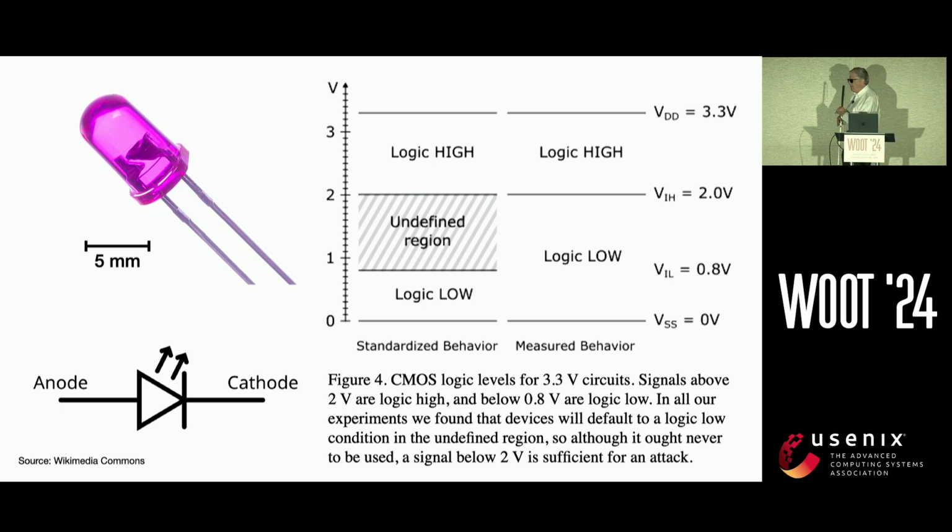When you put light into an LED, it comes out as electricity, but in the opposite direction from the usual current that makes it light up. This violates important assumptions made by the circuit designer. We can force the voltage on a communication bus high or low, depending on how the LED is connected, by hitting it from a distance with a laser.